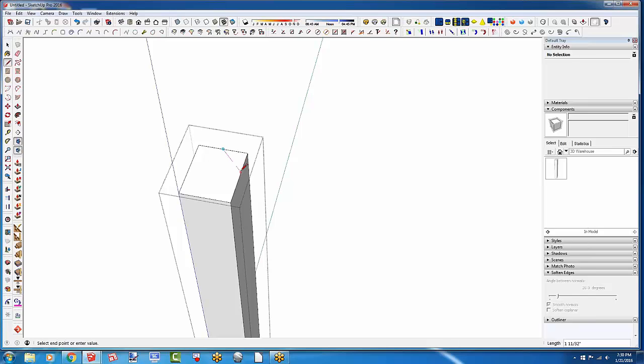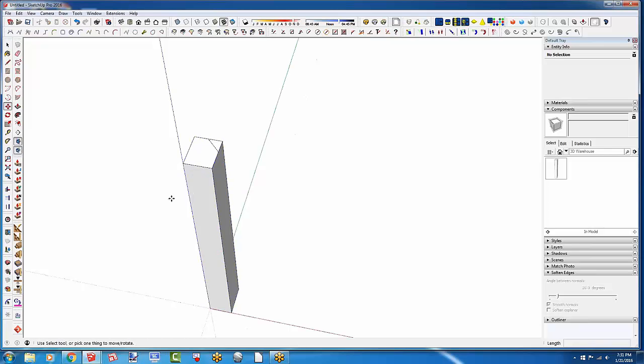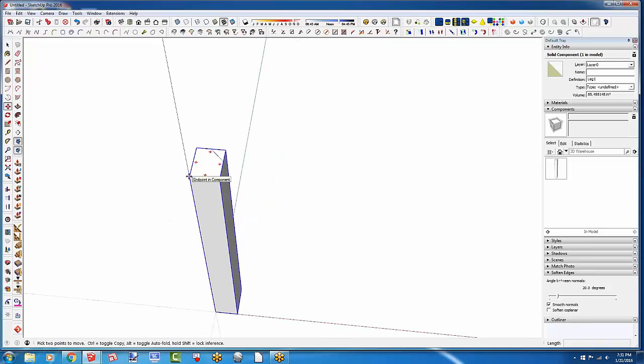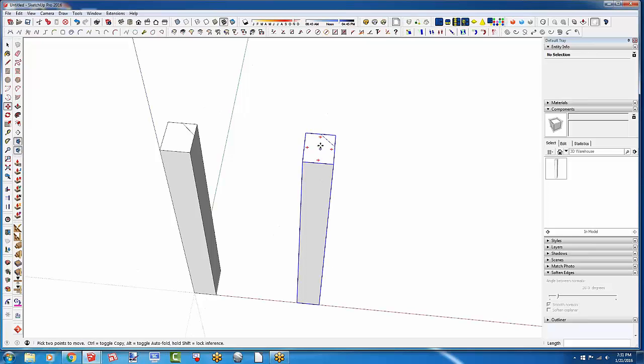Let me do that, because there are 2 things there that are useful. I'm going to draw a diagonal across the top of this leg, just to think of this as a cabinet maker's mark. If you have problems keeping track of orientation, you can put marks like this on, just like you would in the shop, to identify parts. So let's say that this is our table leg. I'm going to make a copy of it over here. And notice I'm moving it in the red direction. I want a mirrored copy of that.